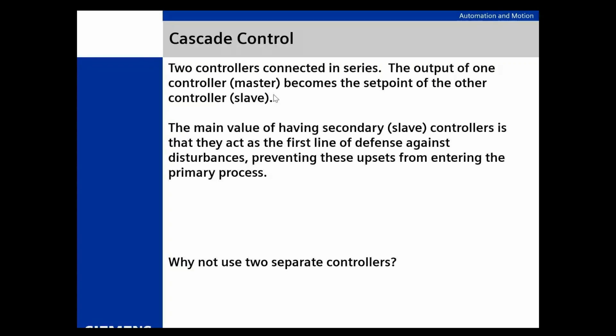The master output becomes the input of the slave. Wow, that's complex. Yeah, it is. Why would you do it? Well, if I've got a process that's subject to massive swings or massive upsets, this may be the way to go.